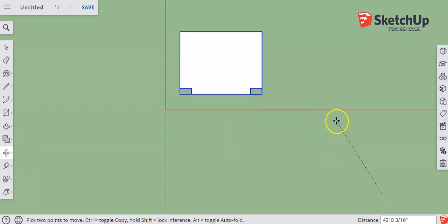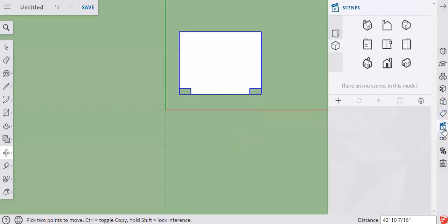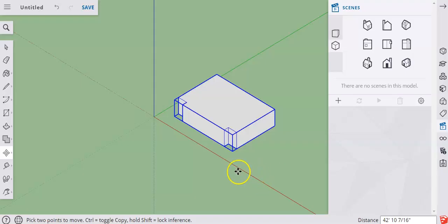And when you're moving 3D objects, sometimes it's best not to click on the object to move it, because then you don't know if you're clicking at 0 height or at 10 feet up or whatever. So if I click somewhere off the object itself, then I can move it along that same 0 height plane without messing it up. Okay, so now I've got my plan oriented the correct way, and if you want to go back and see what it looks like, see, I've got my little cutouts toward the bottom of the plan now instead of toward the top of the plan, which is kind of the standard.